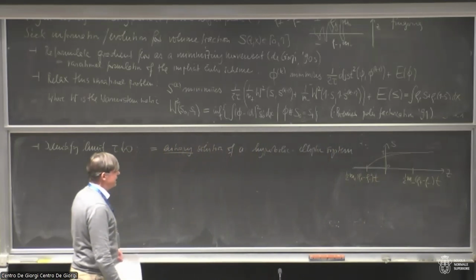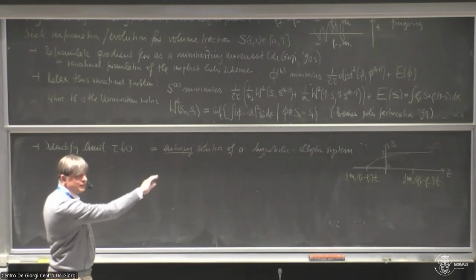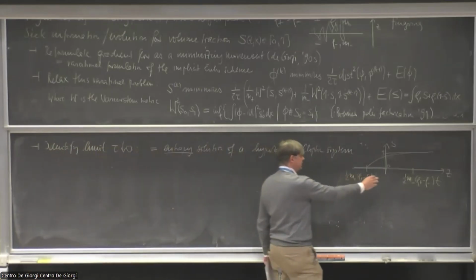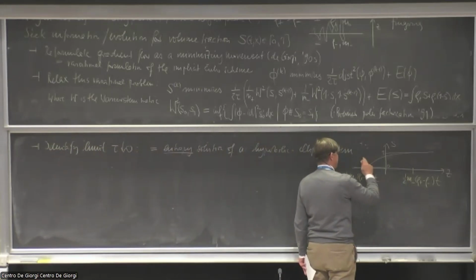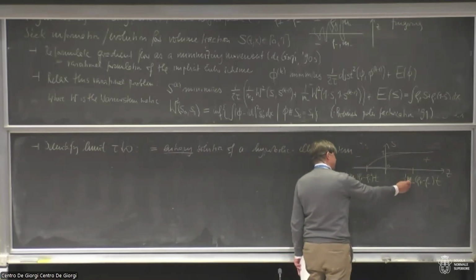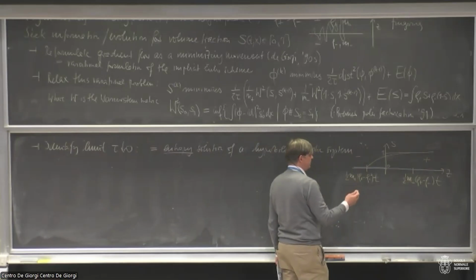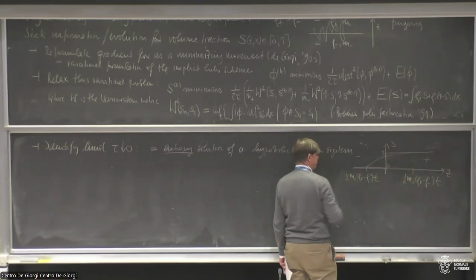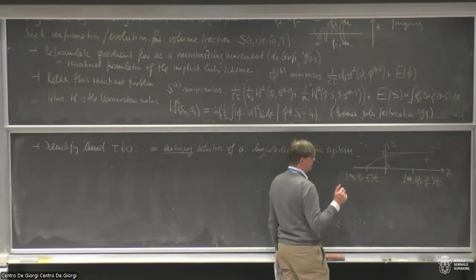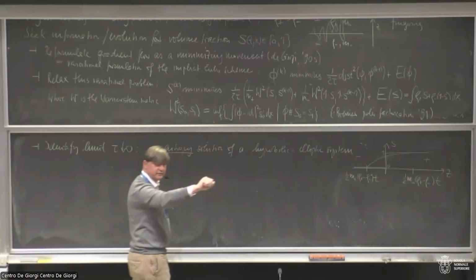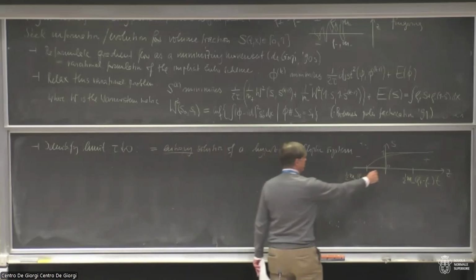So if the mobilities are not equal, it's not a straight line like for Burgers' equation. If the mobility of m minus, so the light phase, here is the minus side, here's the plus side, if the mobility of the light phase is higher, it would tell you that this advancing front is further removed from the original shock than the receding front, which is intuitive physically because the more mobile phase should be able to push ahead quicker than the less mobile phase recedes.